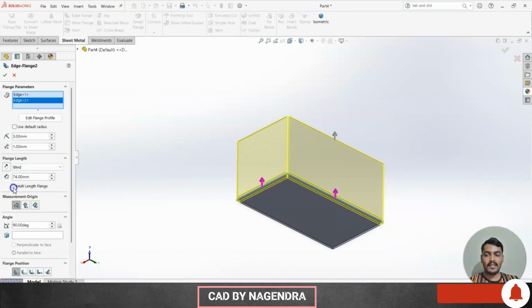Then the multi-length flange is also available. Separately we need to do it. Why? Because in a single option we are selecting multiple edges. For this we want a different height, and for this we want one more height. So you can edit here. For example, I want 60 here, and here we want 74. Like this we can use the multi-length flange.